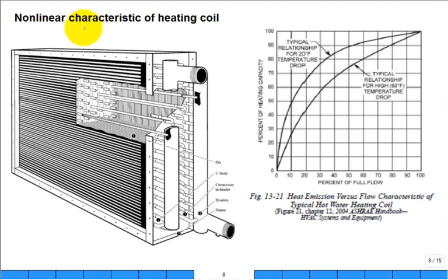When they have a heating coil, you could do this also for the cooling coil, but especially for the heating coil, you'll have some hot water come in, and you want that hot water to come out, and the design engineer will pick a supply temperature. In the South Energy plant, I think it's 180 degrees F. They don't want it to boil. They want just hot water in, hot water out.